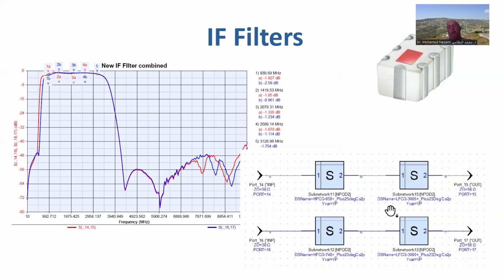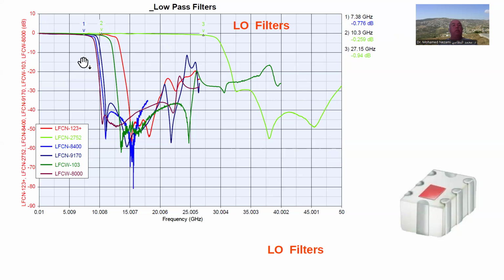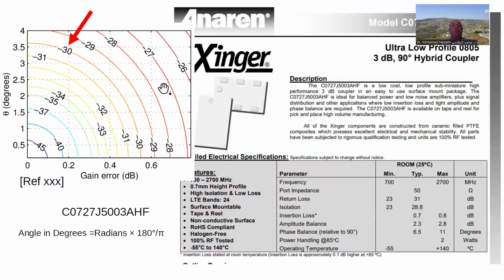And that's basically what I did. And these are the two parts. There are two options in here, which will give me a nice bandpass filter on the frequency band that I want. This way, I don't have to design my own IF lumped component filter, which is terrible to design, considering the tolerances of capacitors and inductors at the 3 gigahertz band. Okay, so this is basically it.